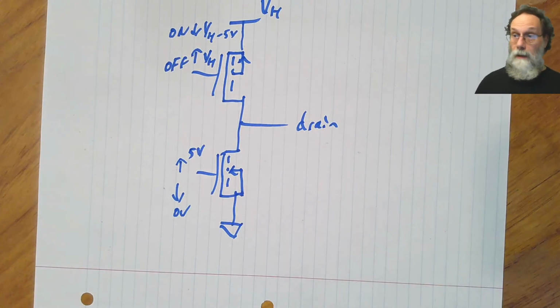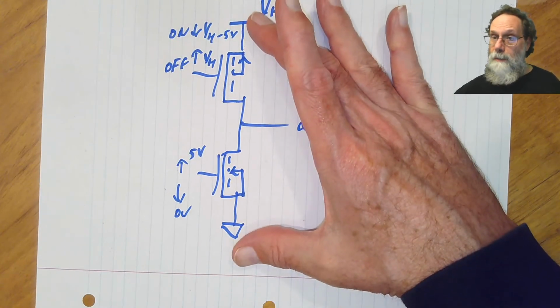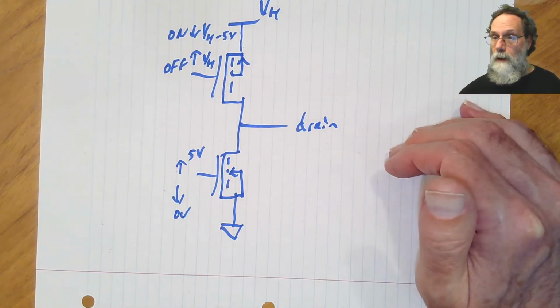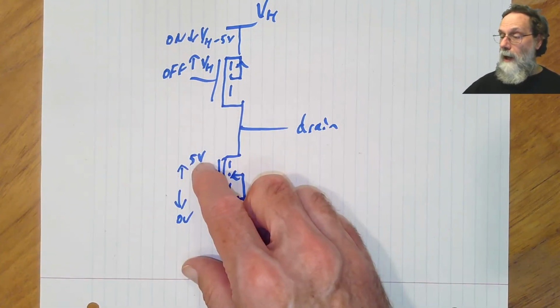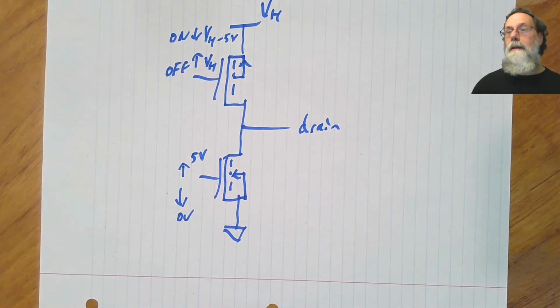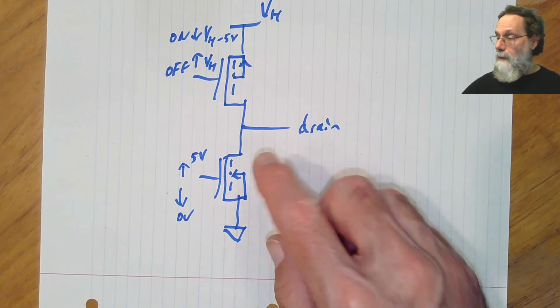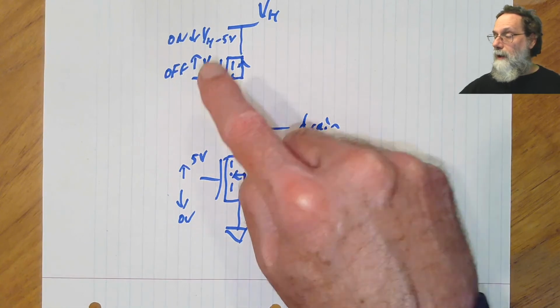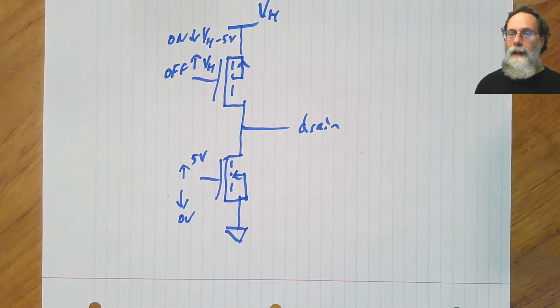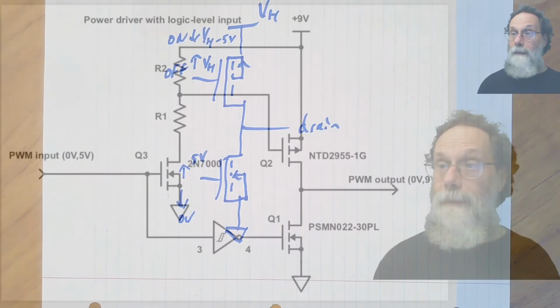And I'm assuming, notice, that we actually have two power supplies here: the high voltage power supply for driving the loudspeaker, and a separate one, perhaps derived from that, that drives the internal logic running at the 5-volt voltage. Okay, so what are we going to do? Well, the simplest thing is to come up with an amplifier of some sort that drives this transistor, shifting the voltage. Let's take a look at one way to do that.